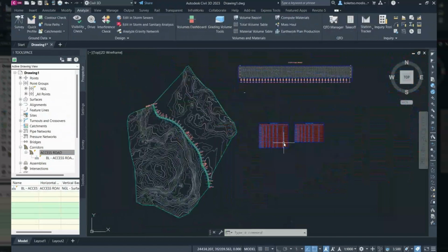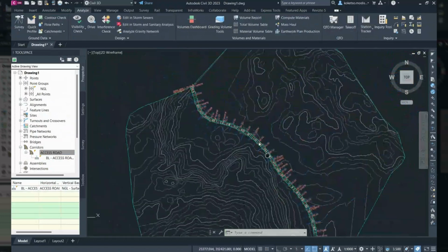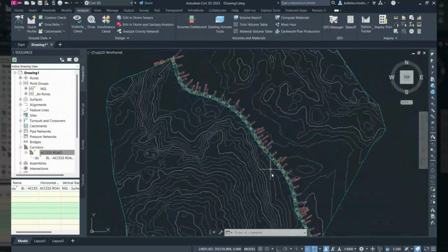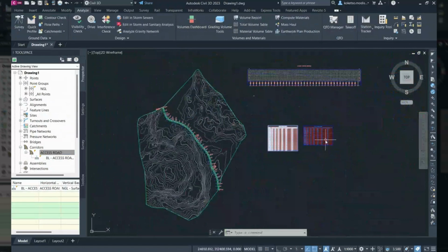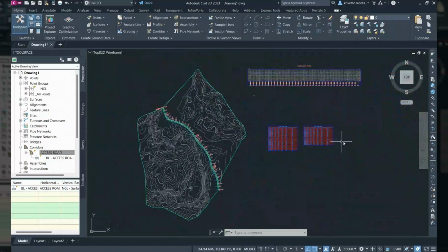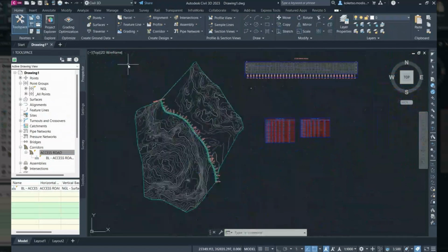After this, you are actually all done. Usually wind farms consist of small access roads towards your wind turbines, but in this instance, we're just gonna create a long access road when it comes to that. So I'm actually gonna save this file with the right quantities, but I'm just trying to show you the logic and workflow of how to calculate quantities for your basic road design. So after you are done with this, I think it's fine. You can save it.